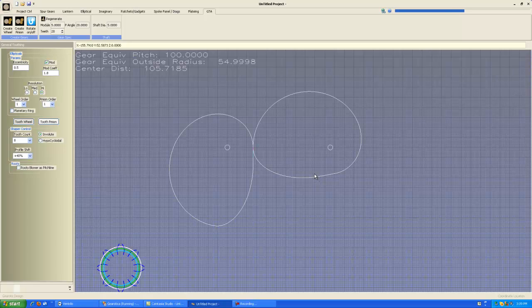There's a bit of a science to ordering the points properly, and it'll develop over time. Let's tooth the pinion and see if we still mess up. Being that we're on high resolution, this takes a little while. The progress bar at the top will make two sweeps, and when it's done its second sweep, it's on the second sweep now, the tooth will appear.